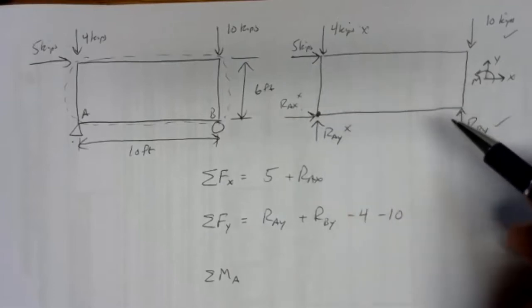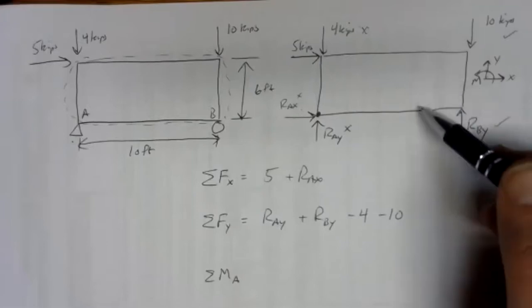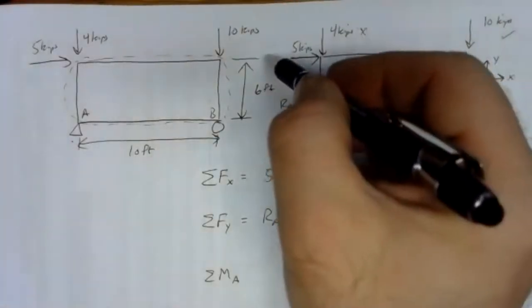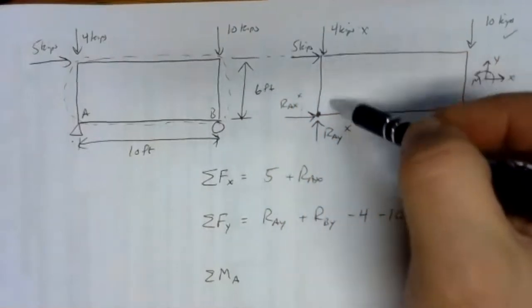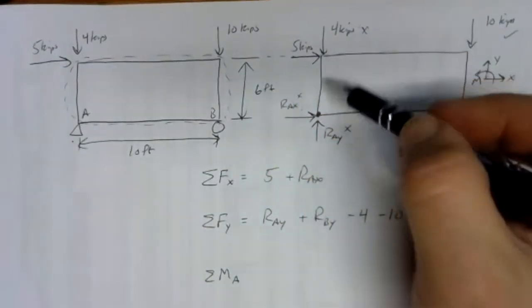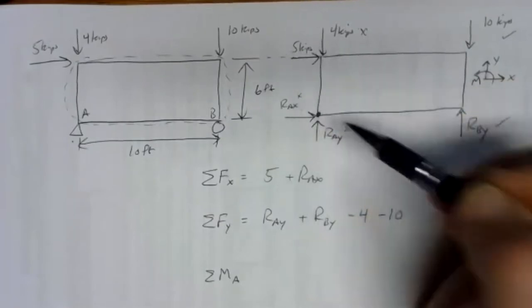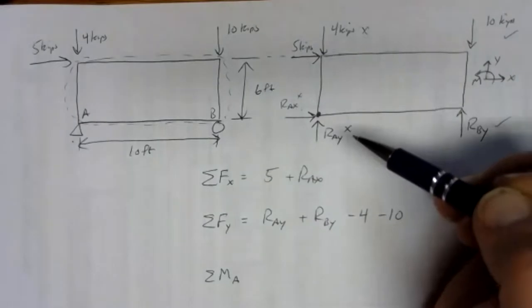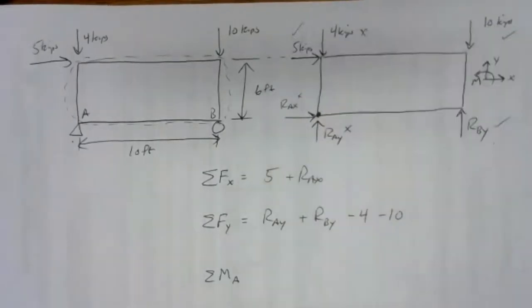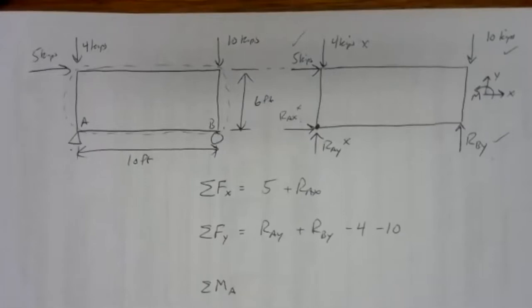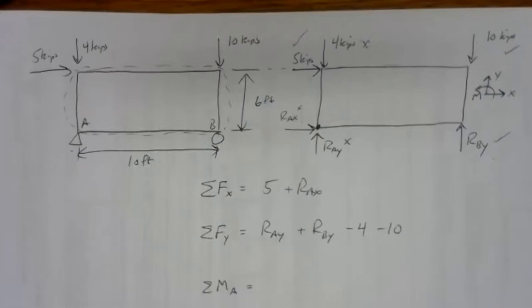But here in a truss, we've got feet of arm here, so it's definitely going to cause a moment. So that 5 kip force, the arm for that is going to be the perpendicular distance from the pivot point, the distance between the line of action and the pivot point. So definitely the 5 kip force will have a moment. So we have 3 forces here that are going to have moments, so we should have 3 terms in our moment equation.